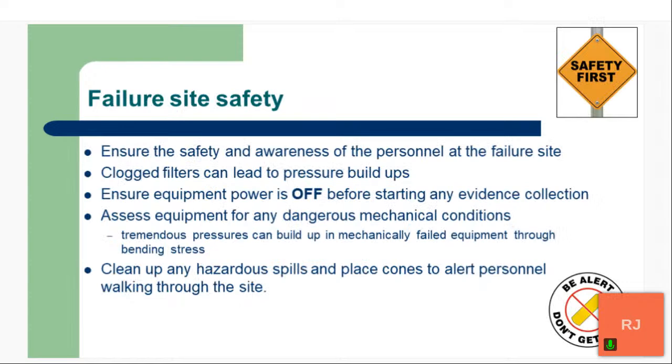So while we're talking about this, we just want to mention some failure site safety. While working around a failure, we want to ensure that the safety and awareness of all the personnel at the site is high. Everybody understands any kind of dangers or issues that could be present due to the failure. For example, clogged filters can lead to a buildup of pressure. So we would want to make sure that we're not getting into any dangerous situations with pressure. We want to ensure that the equipment is powered off before starting any evidence collection. We would not want any accidents because of an accidental powering on of the equipment.